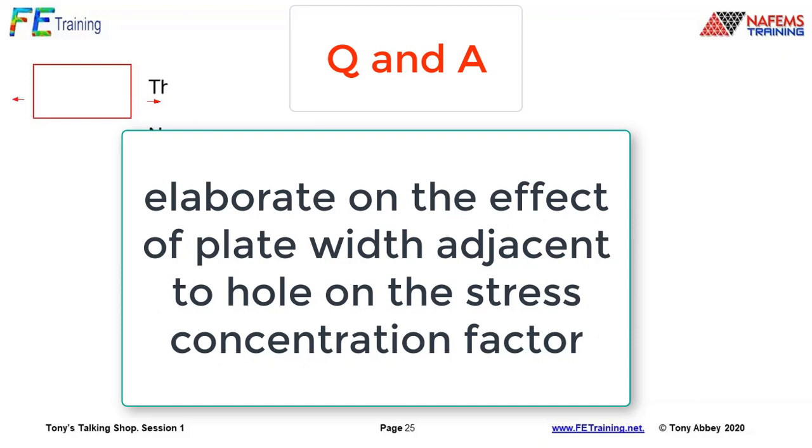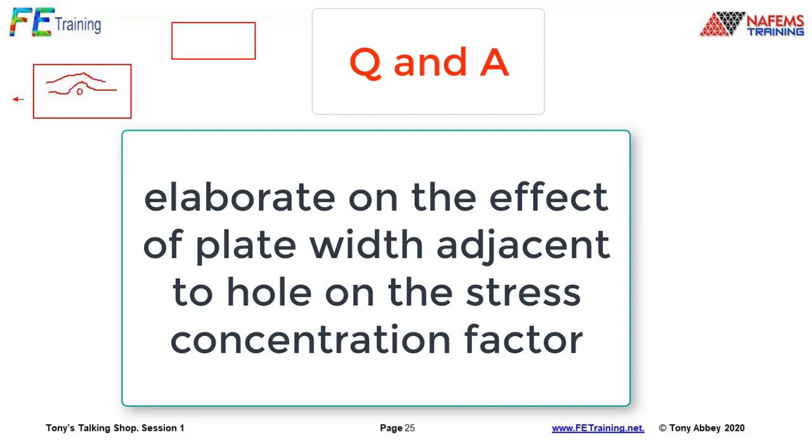So let's say we've got a tiny little hole in there, because basically it's a disruption of flow, is the way I always kind of describe it. The stress is flowing along here, suddenly sees that and has to flow around here, and it gets perturbed in a big way, and that perturbed field goes out quite some way. Now, if we change that and say now we've got a plate and we have a larger hole, that's one way of doing it, the stress concentration factor actually drops.